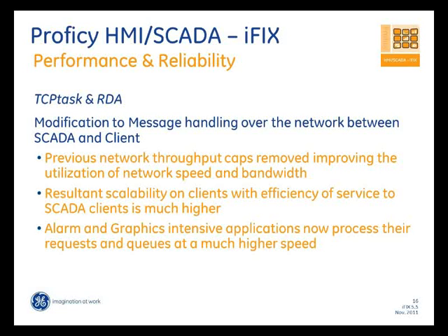What that meant was any customers who had a heavy application in terms of alarms, or number of clients, or number of animations and refreshes happening on the clients that required the SCADA to keep on serving the clients, used to find out that either they faced client dropouts, or the alarms used to come a lot slower, or the whole performance used to go down as they added clients. Now with the new TCP task, the ability to handle network transactions has gone up.